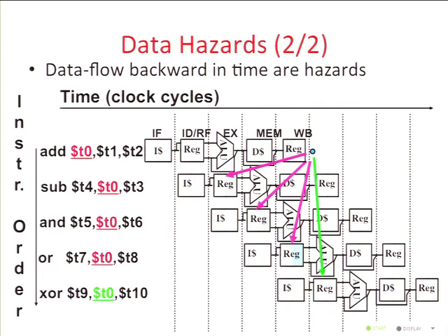Yeah? Yeah, that's not just the wire. There's also a mux. There's a wire, and whenever you have multiple wires coming to the same place, you need a mux. Whenever you have a mux, you need a control signal. It is more time for the stage, but that stuff's really fast. What's tricky is you got to make sure you get the control right. And the control is going to be driven by those things that are in those registers. So it's going to get a little trickier. Yeah.